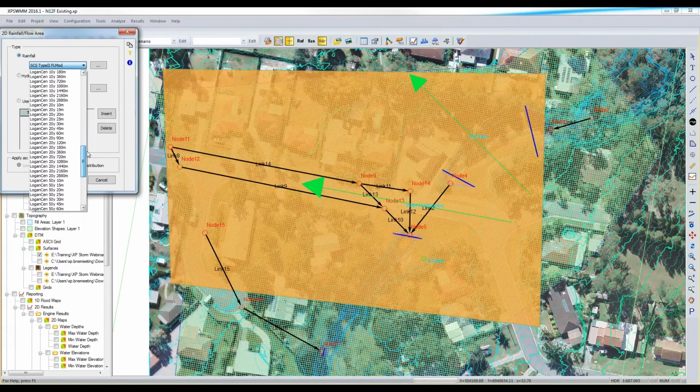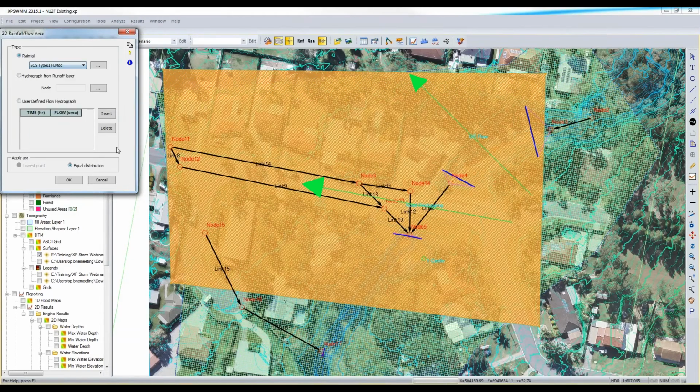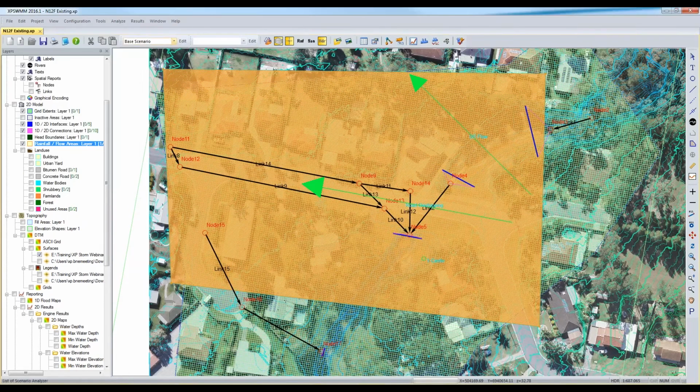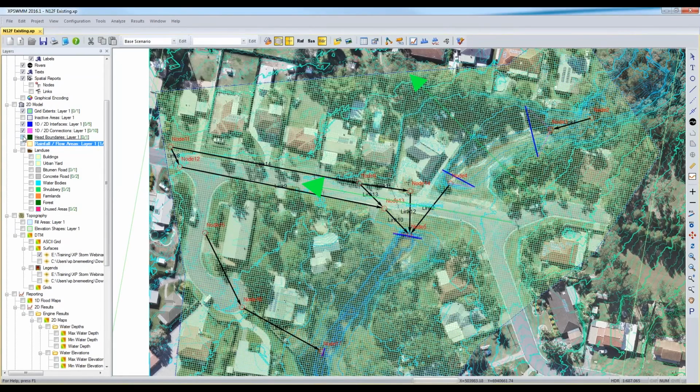And we've actually found, even for this 200 hectare size catchment, we still use about a 60-minute event. It seems to be the peak rainfall event for urban drainage in all of our catchments in Logan. I don't think we've gone external to 60-minute events. It's just from trial and error. 45 won't actually give you a higher peak, we've found. So there you go. That's your rainfall.